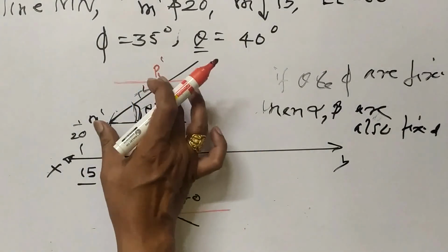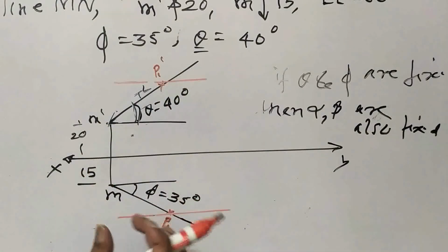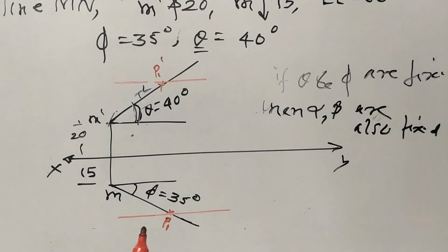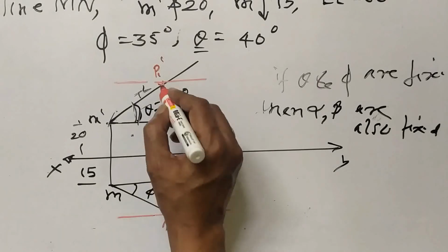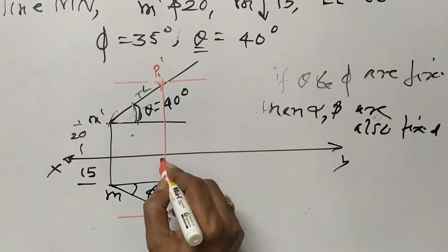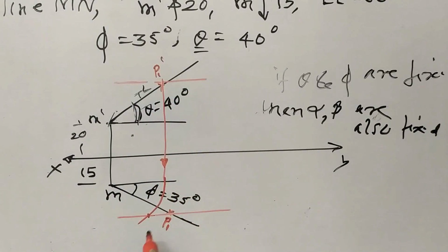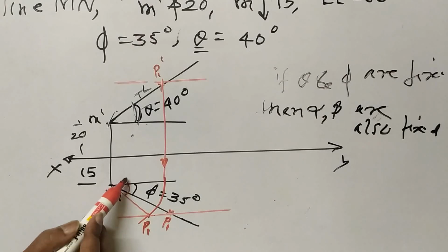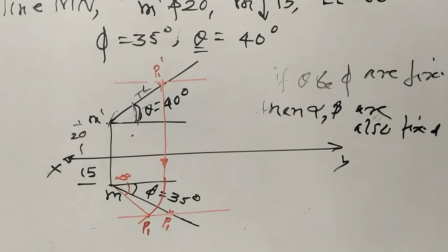And then we have this true length and this true length. For this true length, you can find the elevation length and plan length by projection and rotation. So I will project this much true length here, and then I will rotate it. I will get the P1 point. I will join this. So what I will get is the alpha angle, beta angle here, right?